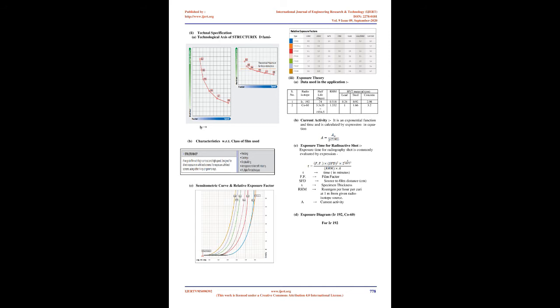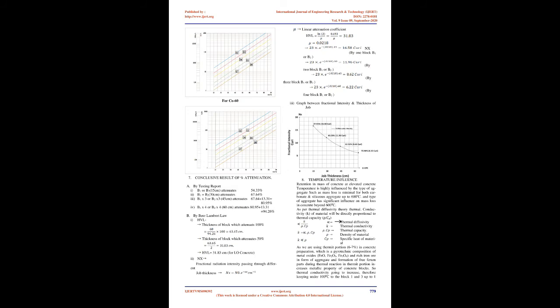3. Sample testing. Radiographic evaluation of concrete. A. Radiations, rays, characteristics. Gamma rays. 1. Wavelength: short, 0.005 angstroms to 0.5 angstroms. 2. Frequency: more than 10^19 Hz. 3. Velocity: the velocity of light, 3 x 10^8 m/s. 4. Penetration: can even pass through 30 cm thick material. 5. Deflection: no effect by electric and magnetic fields because of no charge or mass. 6. Energy: high energy radiation, energy greater than 100 keV.